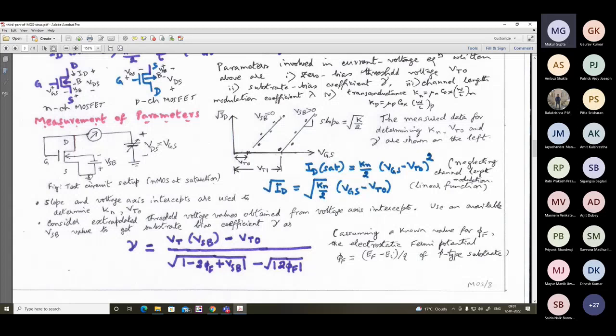Suppose you have got a stack of transistors, for example cascode structures. In analog you have studied about that, or even say a NAND gate. Stack means a series placement of the involved transistors. Then for the bottommost transistor only, the source is connected to body. But as you go higher up, suppose in a 5 input NAND gate, you have got a series placement of 5 transistors in the NMOS path.